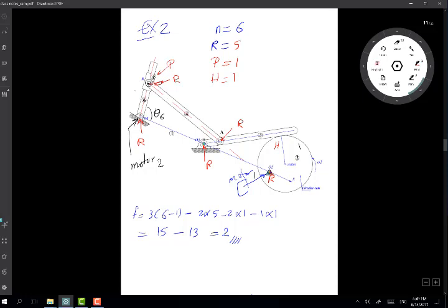And together with the angle of this motor here, I can force point B, the slider link number 5, to follow a trajectory that I need to have in my machine. So if I need this specific point to follow a specific trajectory, I need to change this angle here together with this angle here in whatever way will cause point B to move on that trajectory.